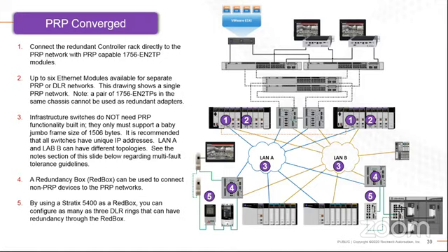The other example that I have here is parallel redundancy. So again, PRP for short. Very similar design. We'd still be having segregation between your upper level network, like your upstream for the HMI historian communication, but then also segregation for your IO network. The IO network can be mix and match. So you can have ControlLogix or Flex IO.